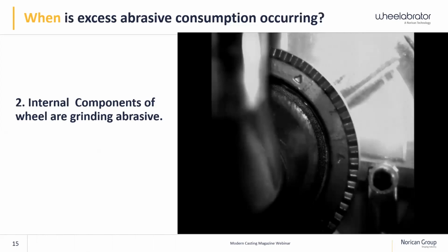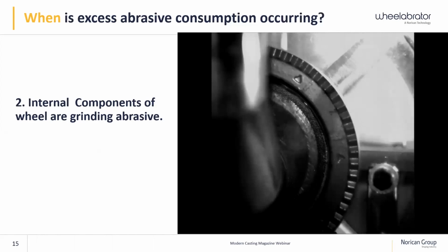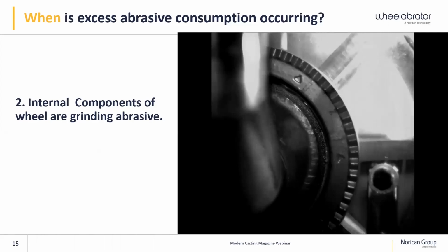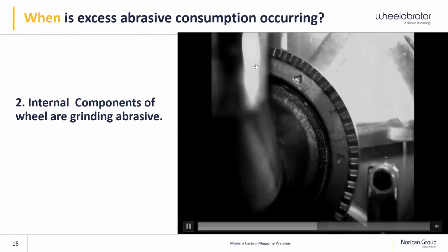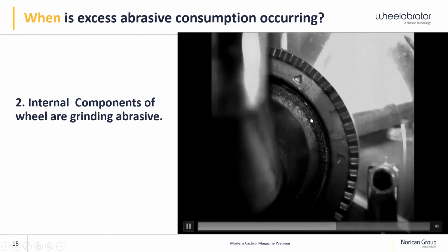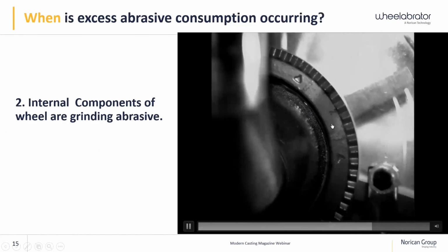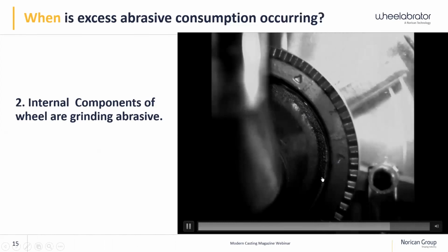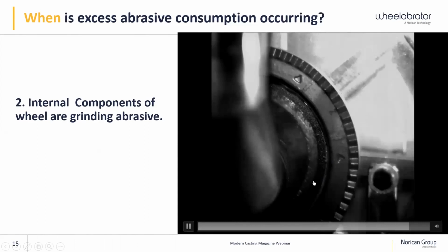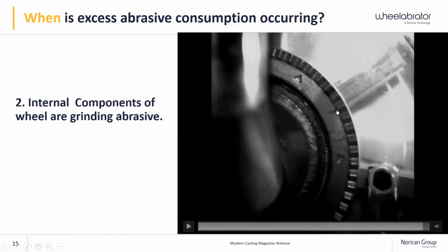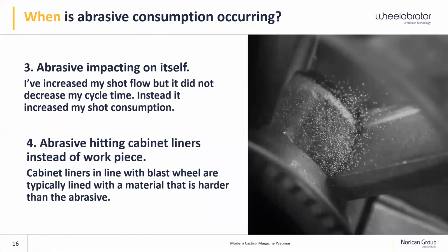And what I really want you to lock in on is the impeller rotating around, and you'll see that wave of media. I'll try to use my cursor to show it. This wave of media right in here. So this is the impeller rotating around. You can see the arrows indicating the opening of the control cage right here. So that media in that gap right there is what is riding around there and then transferring over to your blades. You know, it's a violent action of what's going on in there.